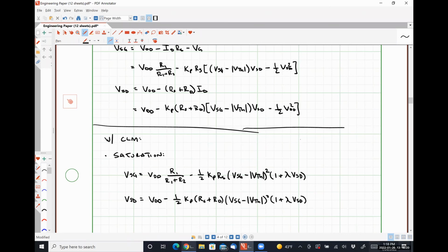With regards to the kind of problems that I expect you to do some numerical analysis on, it'll be things like, I give you maybe 3 or 4 simple circuits with a bunch of voltages given, and you have to tell me which mode the things are operating in and prove why you say it's operating in saturation, forward active, or triode, depending. I'm mixing terms here because I'm not telling you whether it's going to be a MOSFET or a BJT.